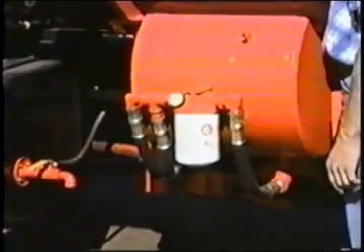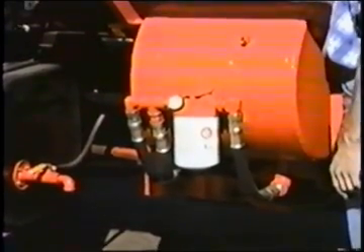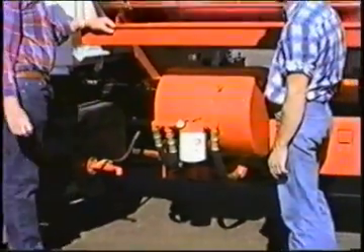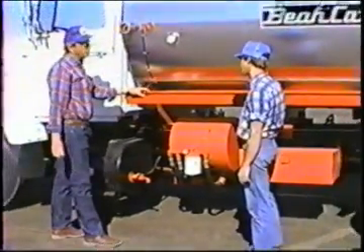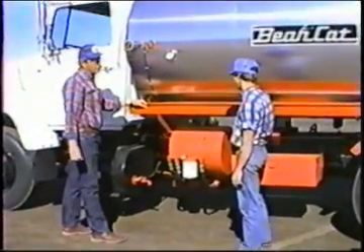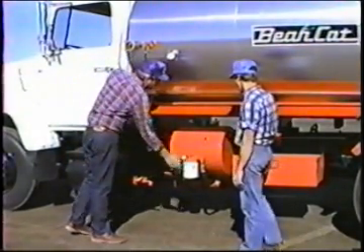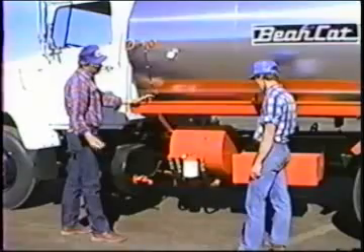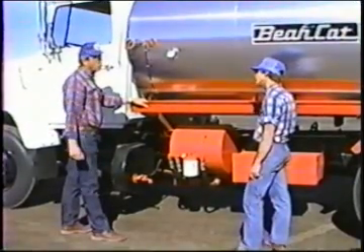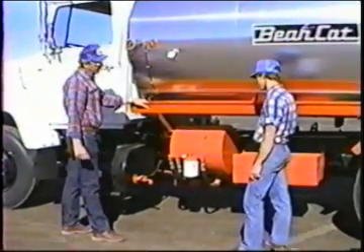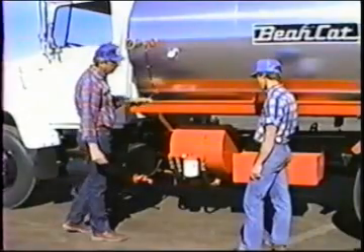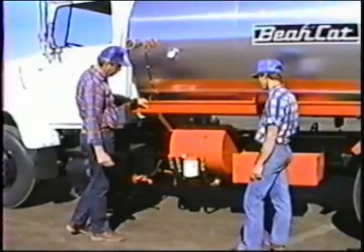Typically a filter will go an entire season. If you're running a lot of water, that is, if you travel when it's raining quite a bit with the machine, you tend to pick up moisture in the hydraulic system, and moisture will plug up the filter quicker than anything. Easy deal. If it gets up in the neighborhood of 10, time to ask for a new filter. Again, type F, automatic transmission fluid.